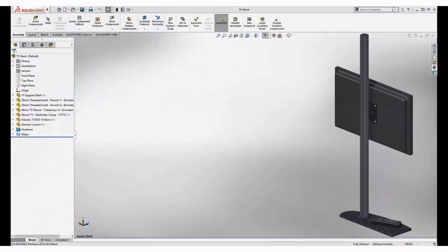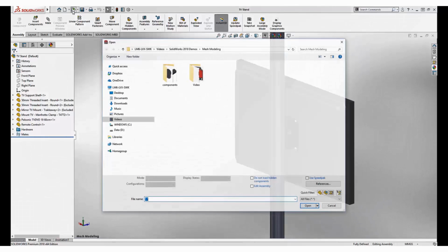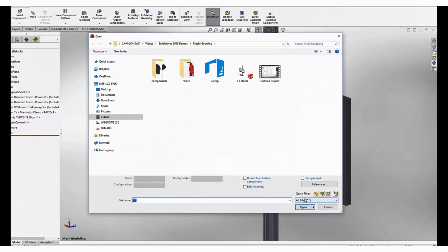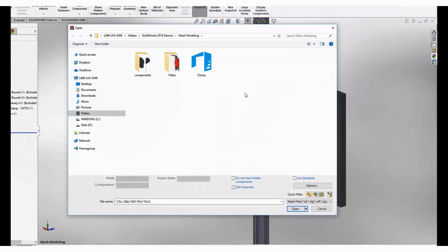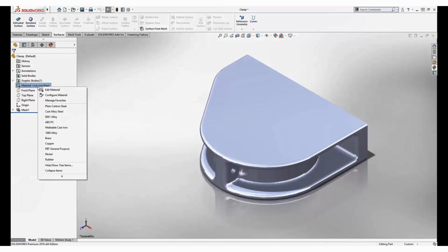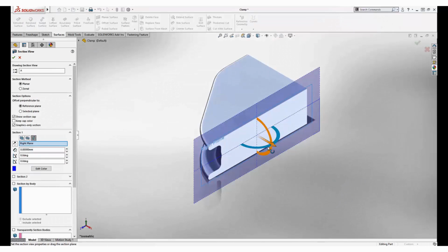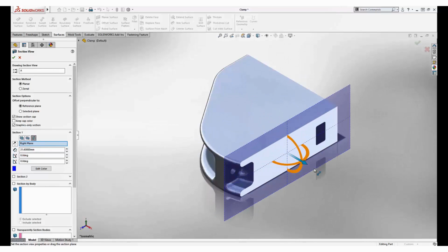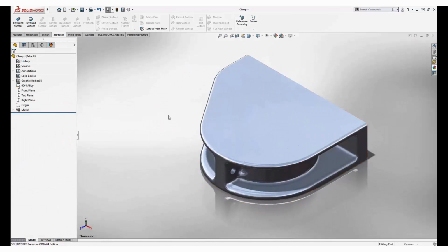Mesh modeling is getting more popular with the trend of using more 3D scanning and 3D printing. SOLIDWORKS 2018 introduces new ways you can utilize mesh data for a variety of formats such as STL, OBJ, and additive manufacturing files. First off, graphical mesh geometry now supports material textures and real view appearances. We can now perform sections on graphical mesh data as well, and as a result, we can now better visualize and fully understand our mesh geometry right inside of SOLIDWORKS.